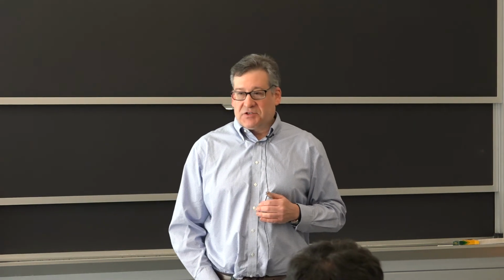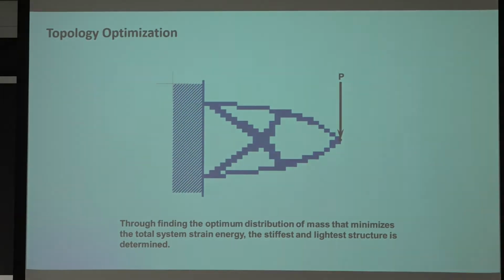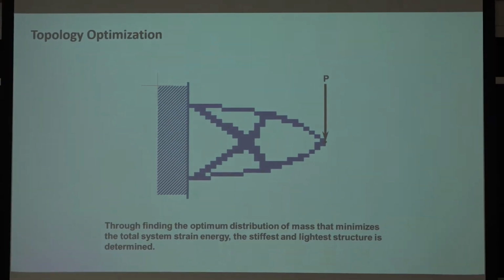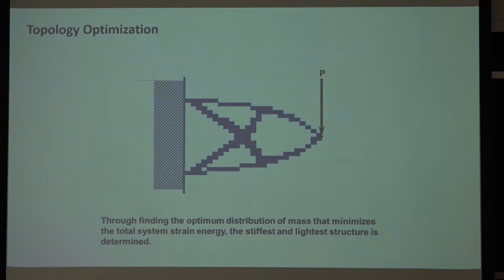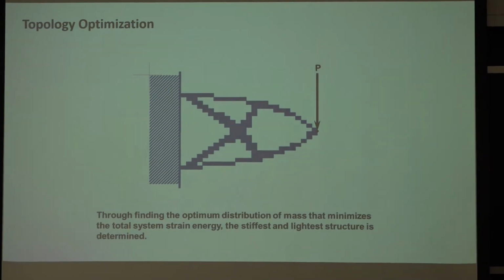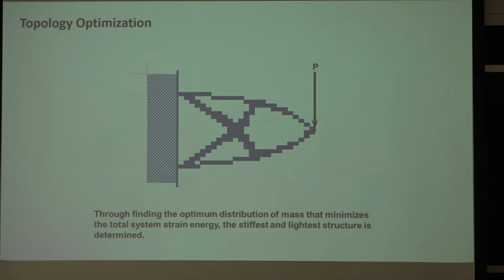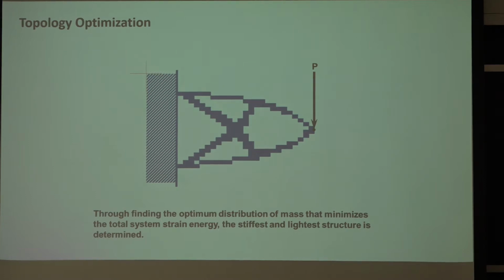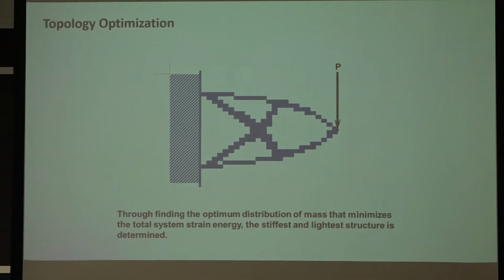Anyway, just to start our lecture here, last time we talked about topology optimization. We talked about the idea of a packaging volume. That's a place where you can put structure, all the places you can put structure. You can't put structure through somebody's head if it's the interior of a car. You have to leave that out.